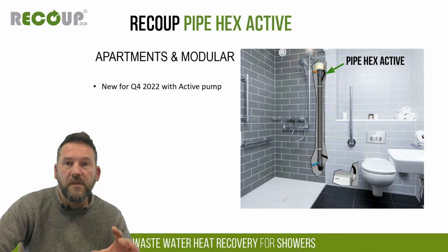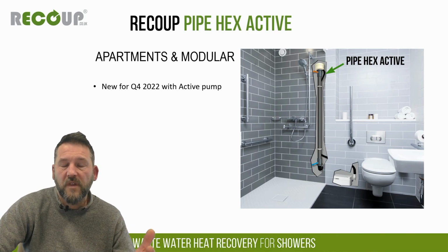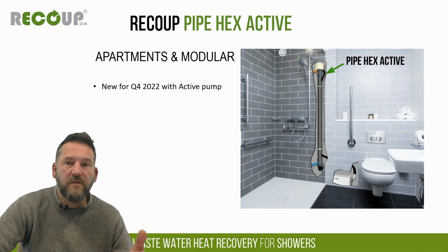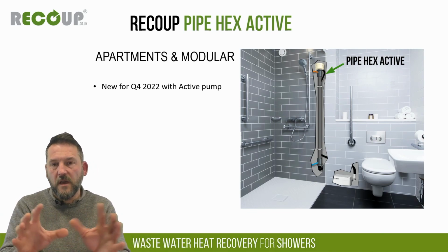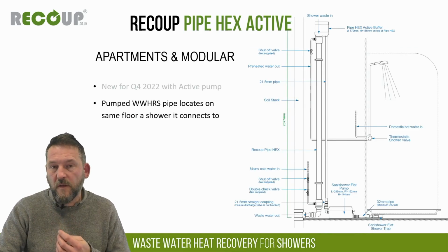Whilst the wastewater heat recovery can be installed with reasonable access, so behind the shower wall or something, the pump unit itself does need to be accessible. So we're seeing this being designed into under sink vanity units and things. That flexibility of design is really quite important in practice.